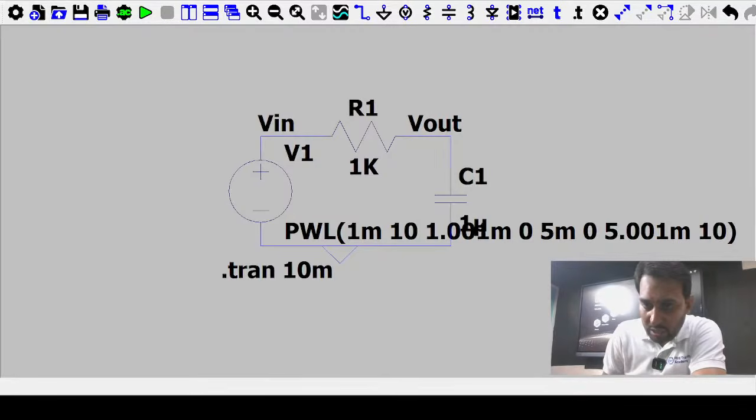In real IC design, what is the very first step when designing a circuit? Is it finding W by L using the ID formula? It depends on your design specification requirement. Most of the time you will have an ID and a power dissipation.